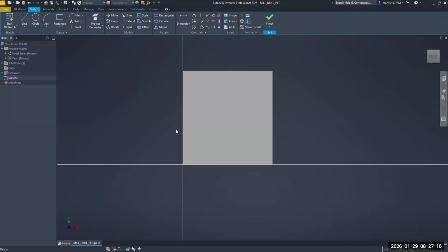And the only way I can make those lines visible is I have to go to this menu item called Project Geometry, Project Geometry. You with me, Zaya? Now go around, look, click, click, click, click. We've selected 4 lines. Do a right click, please, with your mouse. Select OK. Very important what we're getting ready to do next.